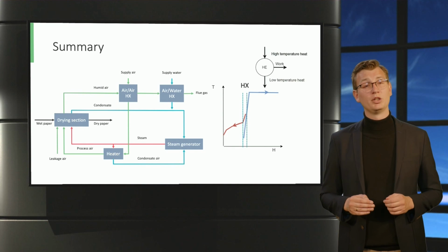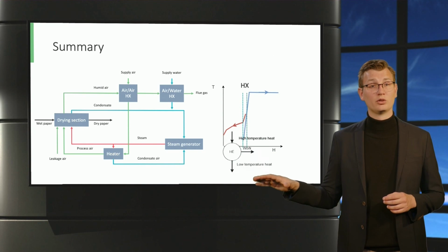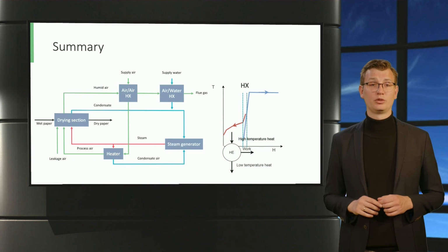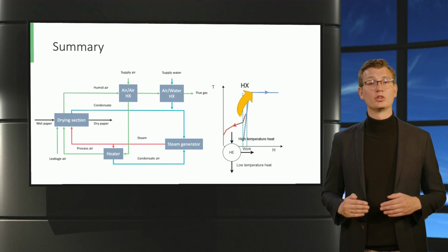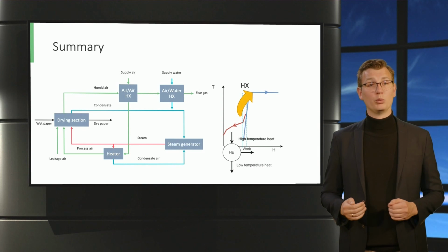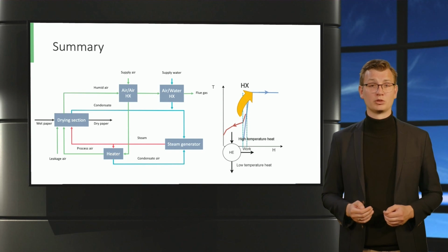A heat engine could be an interesting option to supply this heat. Otherwise, the engine could try to utilize the energy wasted through the flue stack. Another option is to use this waste heat and convert it into a higher temperature heat with the help of a heat pump and reduce net heat and cooling requirements.